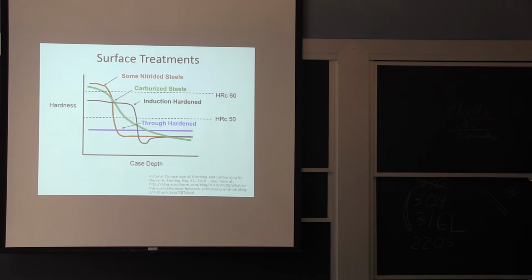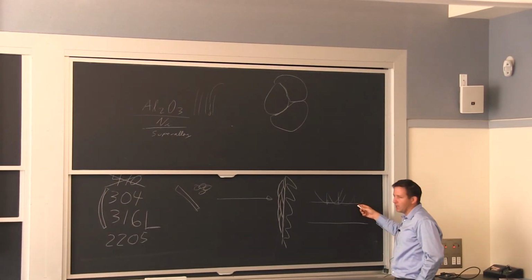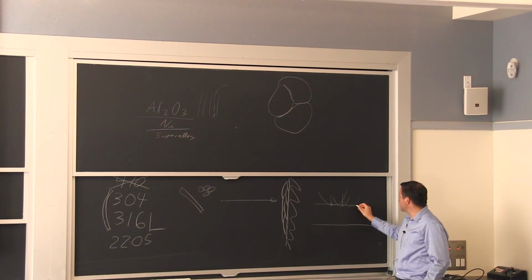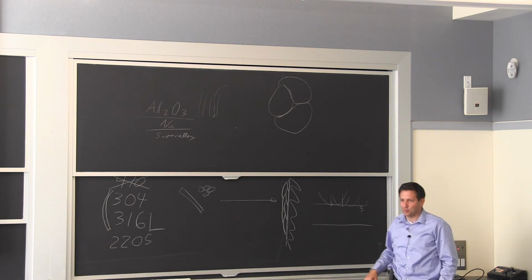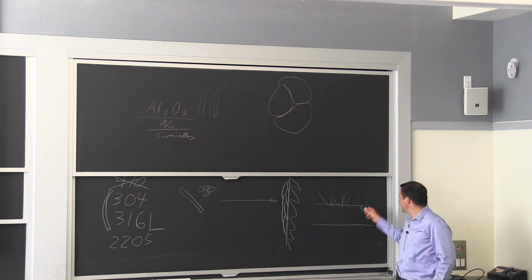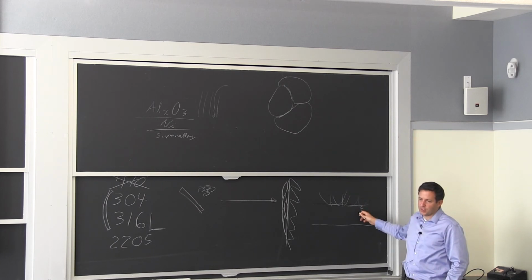We used it quite a bit. The idea is, say if I start with a fresh surface, instead of trying to harden it through any surface treatment that we talk about, I just come with beads, and then I'm coming multiple times. So this is essentially, could be a little bit like sandblasting. So I'm shooting beads on the surface of a superstructure for the aircraft. And each time I hit the surface, it's like forming an indent. But if my beads are small enough, what I do is I get a compression layer on the surface by poking it, and then I get tension underneath. Unfortunately, you can't win this battle. So you're increasing the surface resistance, but you do end up with tension underneath.